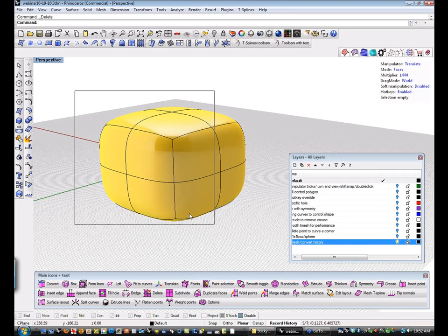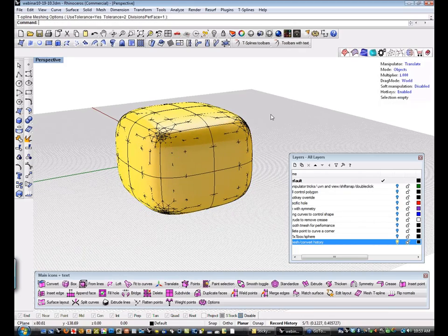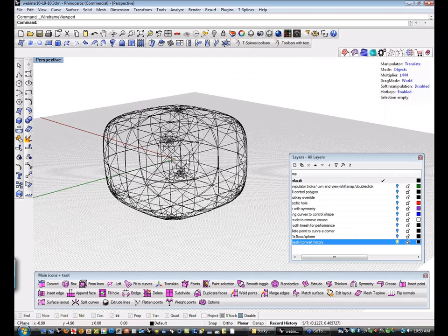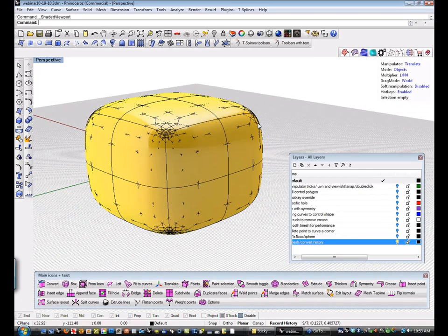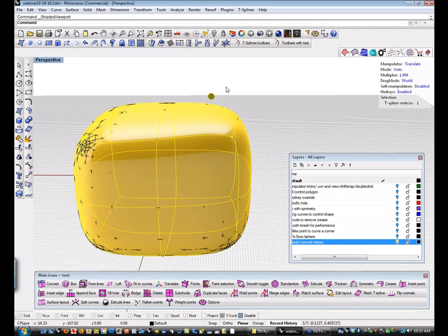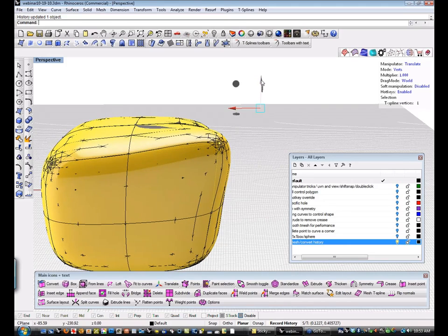So if I pick this object and I use the tsMesh command, I'll just use the default settings for example, you'll notice that I get a meshed object, but it kept my original T Splines object, and if I modify this, you'll notice, lo and behold, my mesh updates to match.